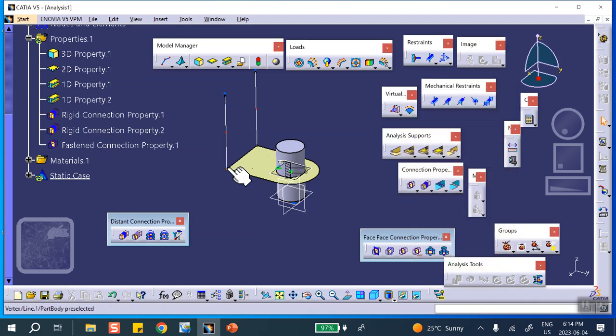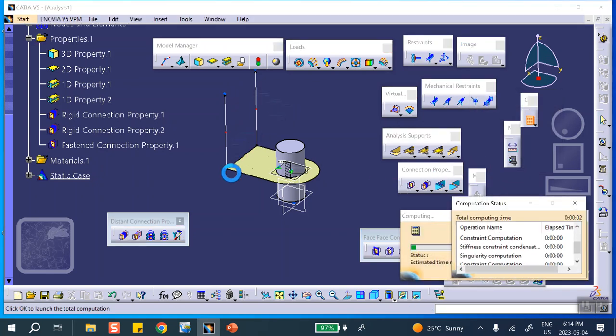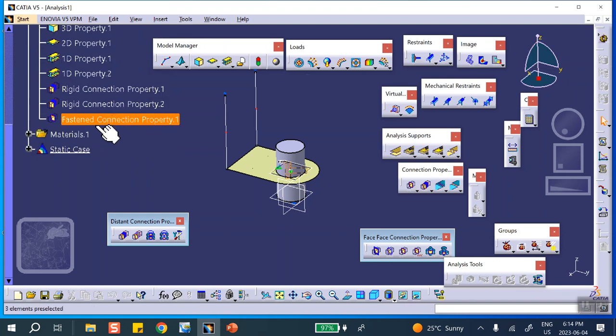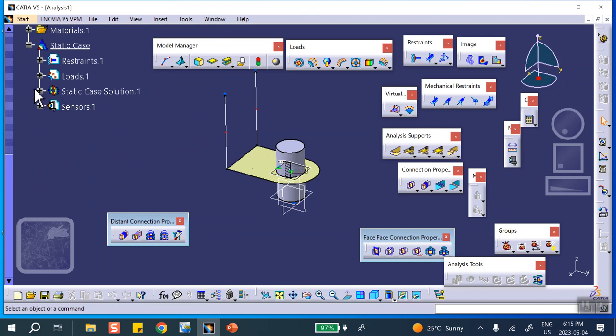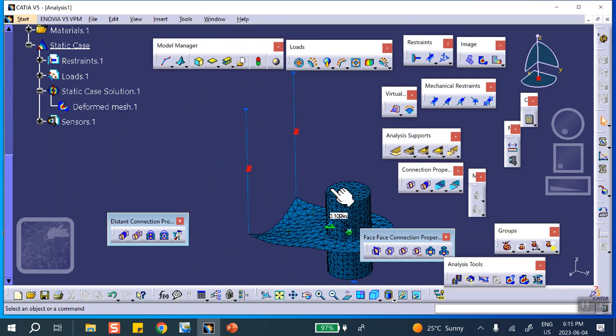If I run it, I will see that that thing does not bend down here, but it will bend up there. Okay? Let's run it. It will bend up there, but not down there, because the same thing should happen on the very top. In other words, rotation about X and Z should, X and Y, and in fact Z should be left alone if that's a cable. So let's check it out. You see, this is not bending. However, on the top, there is a restriction on rotation about X and Y.